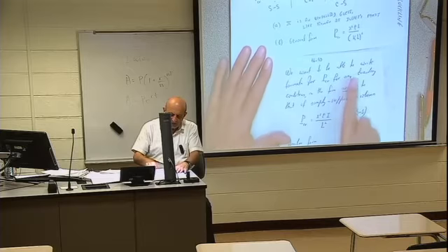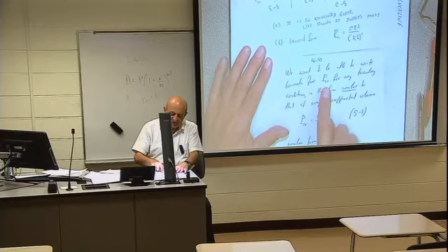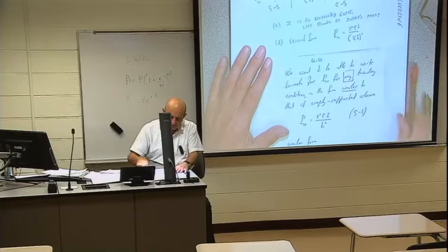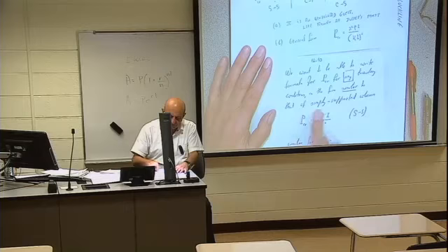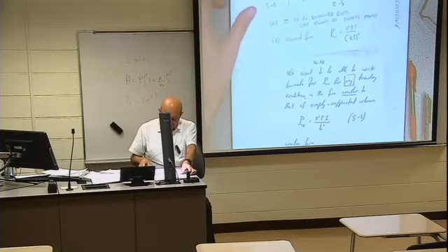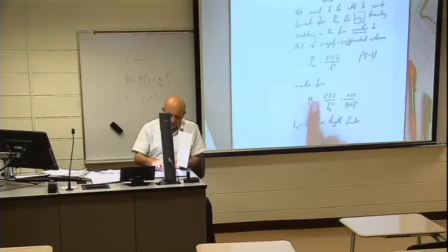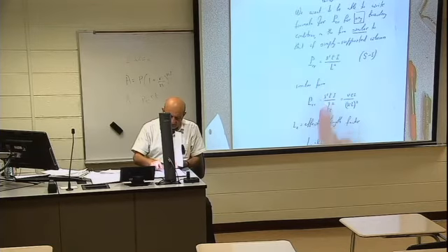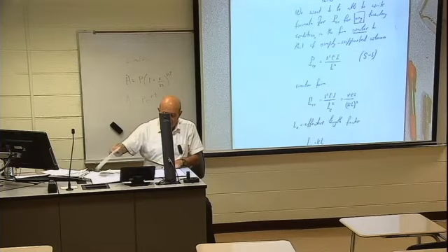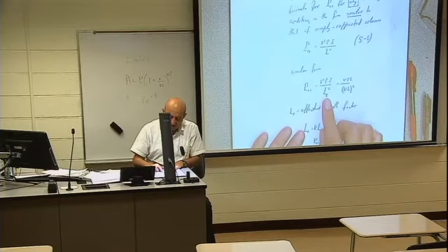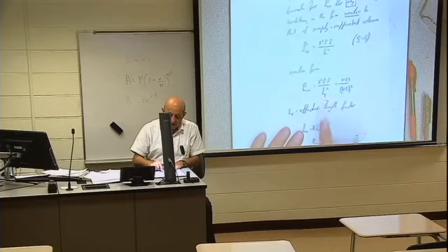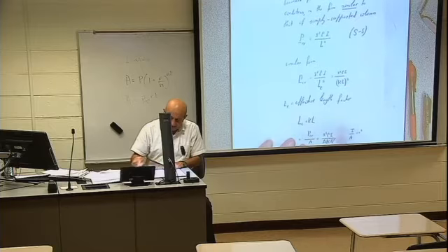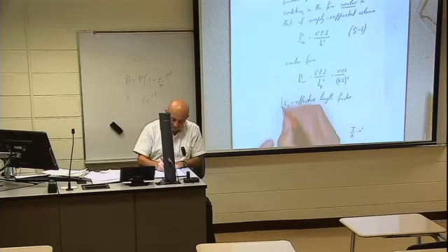We want to be able to write formulas for P critical for any boundary condition in the form similar to that of simply supported column. So that is simply supported column, that is an expression. A similar form will be not to write L, but some effective length, LE. This LE then equals K times L. Effective length factor.